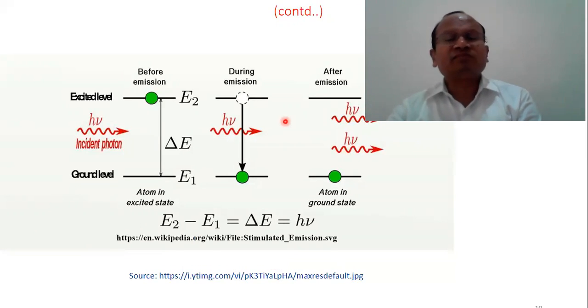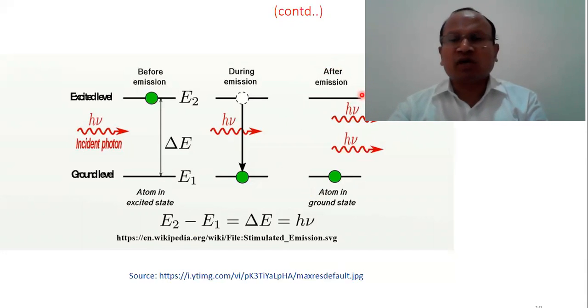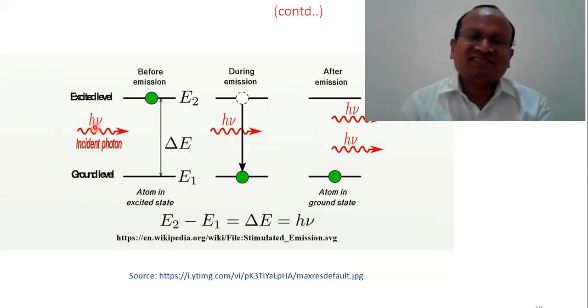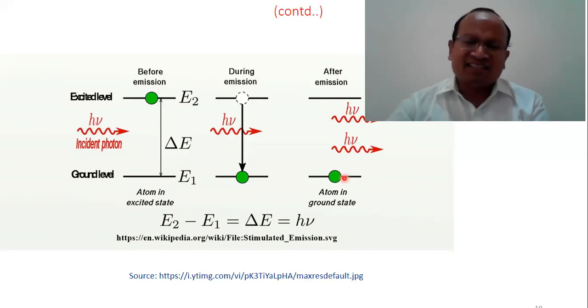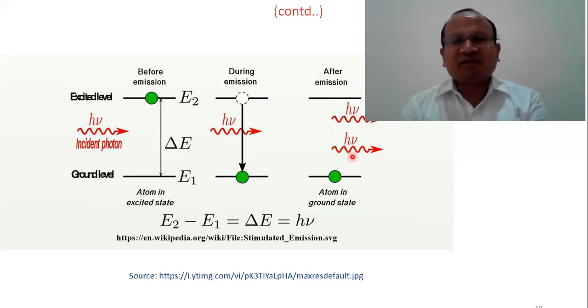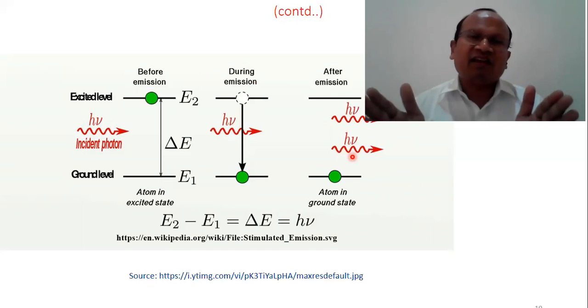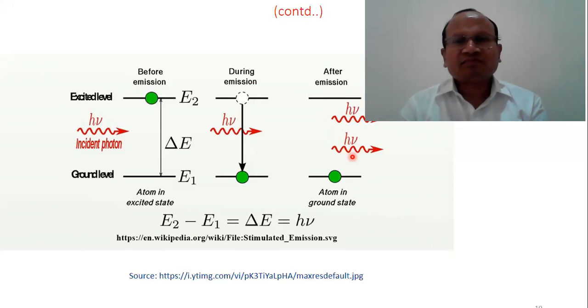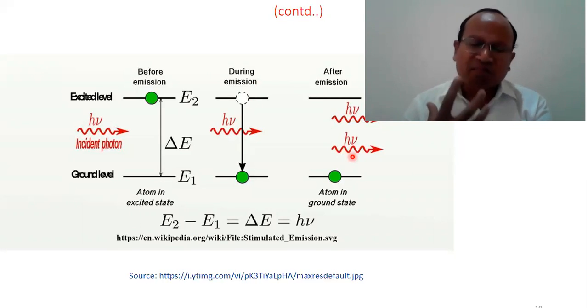We have already discussed this diagram, and we can understand how in the third case you can see the stimulation taking place. The photon which is coming as the input photon is common in all the three diagrams. This stimulates the falling carrier, this electron, and after stimulating it generates a photon, and then it has to settle down. It reaches the ground state, but what is the outcome? As a result, we have obtained two waves in the same direction. When we have hundreds of such waves, confined in a certain cylindrical or spherical tube-like structure, that is what we see in a laser. It becomes a powerful light beam.